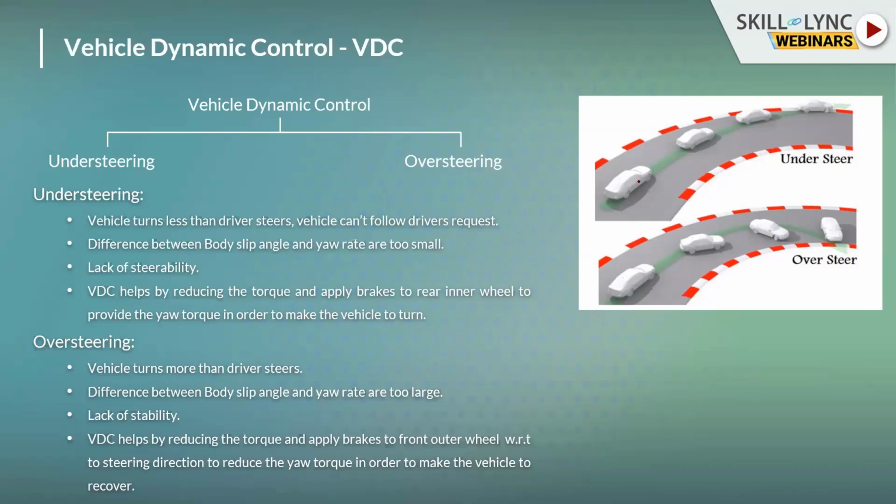It has too much power, so it keeps pushing the vehicle along its translational velocity, because it has too much inertia. We are not able to divert the inertia. It keeps pushing the vehicle instead of turning. Because of that, it is understeering.